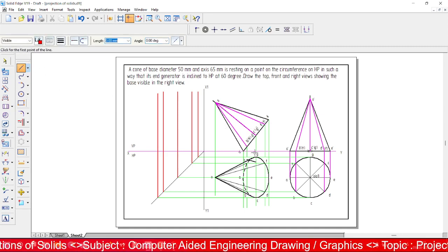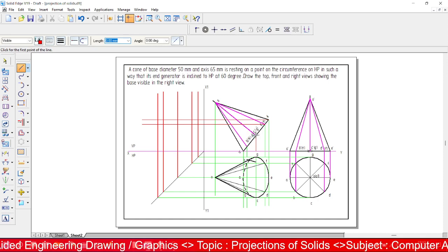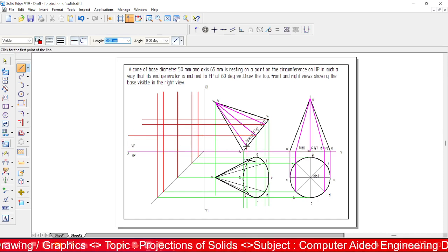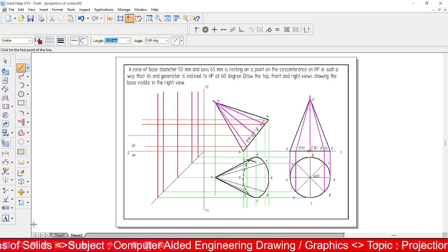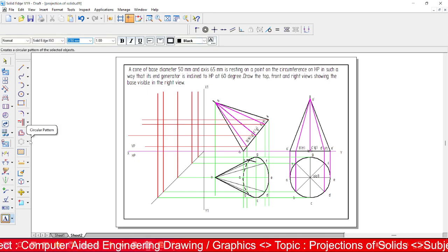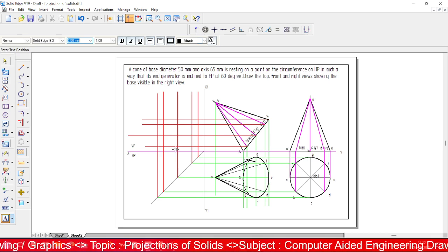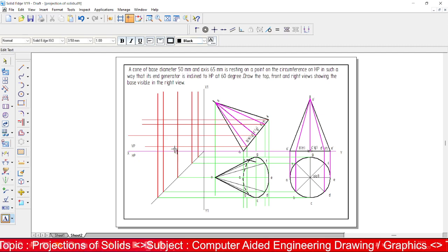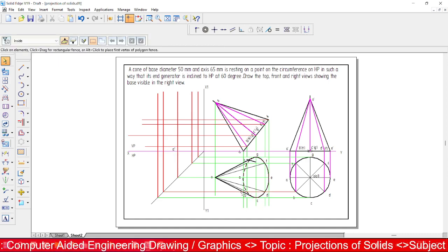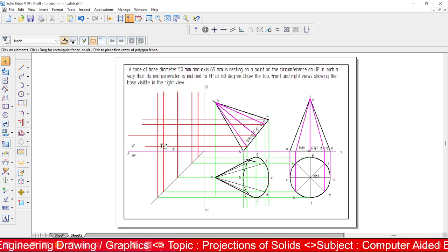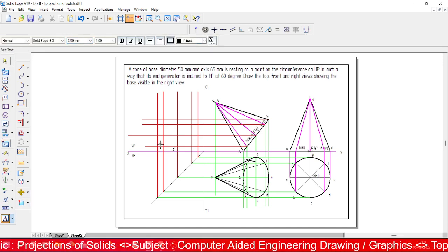Now similarly you draw construction lines from previous stage front view. Okay. So again identify the coinciding lines. Okay, so just identify coinciding projection lines. So now this is what refers to the AE. Now let us go here. You got a point here. So let us mark this as A double dash. So now you got a BD. So just go here. So you got a point B here. Let us mark this point as B double dash.